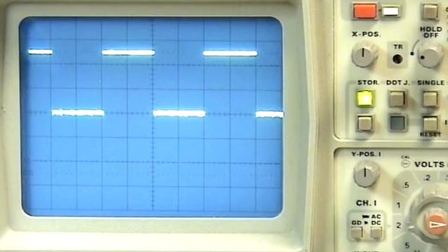A reference mark on the grid foil corresponds to 50 milliseconds. You can clearly see that after two reference marks, which corresponds to 100 milliseconds, the potential at port P2.0 is negated.